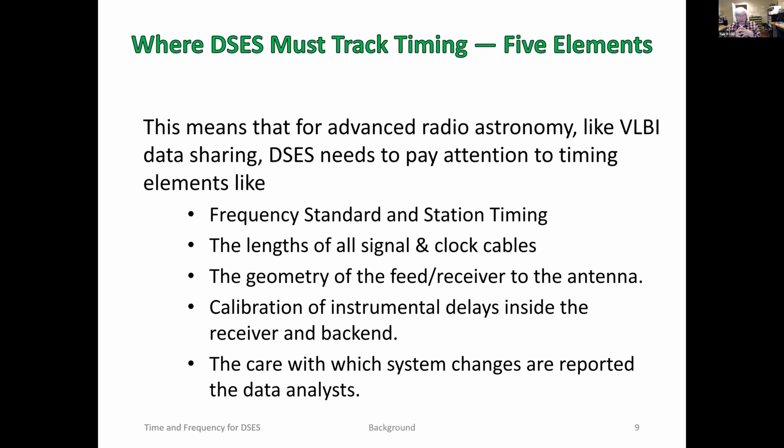All of the delays in the system, the group delays in our amplifiers, everything would have to be measured and categorized, and that includes the precision time and frequency system, which is relying on a calibration from a GPS source, would also need to have a precise measurement of the group delay in its antenna and the delays on the coax to the GPS receiver and the internal group delays in the receivers.